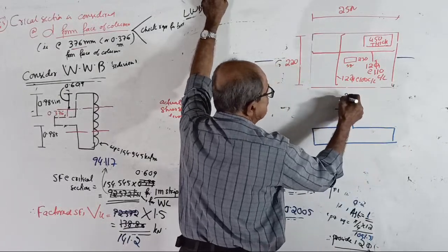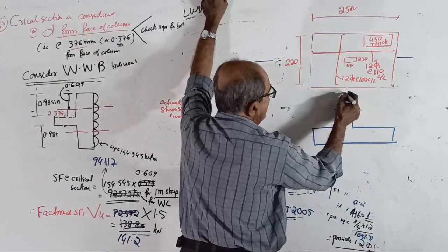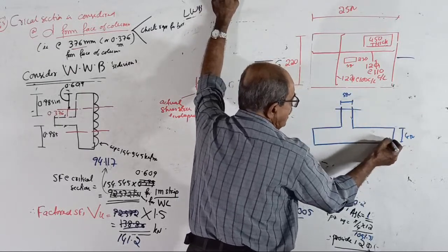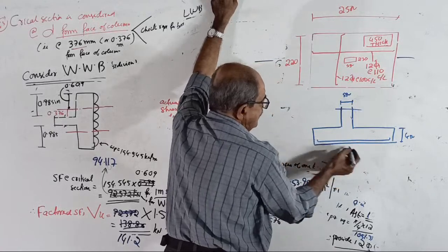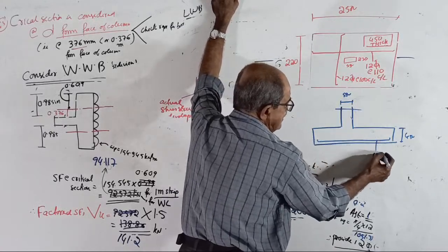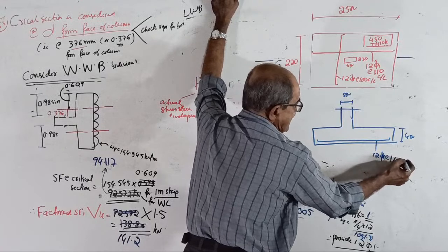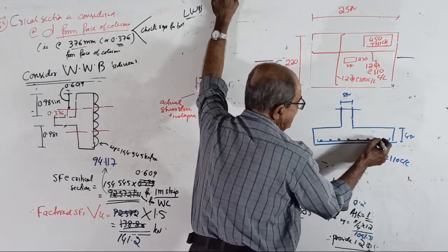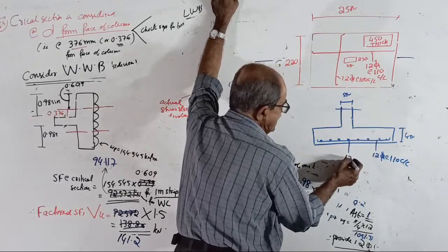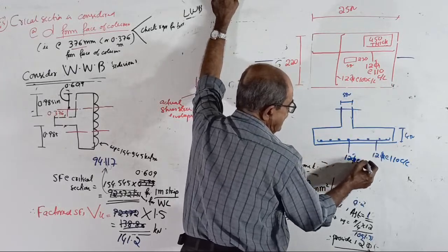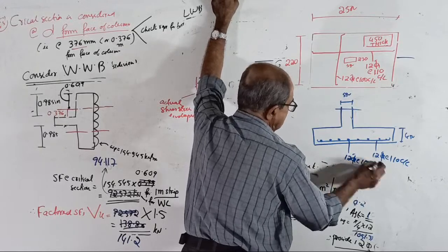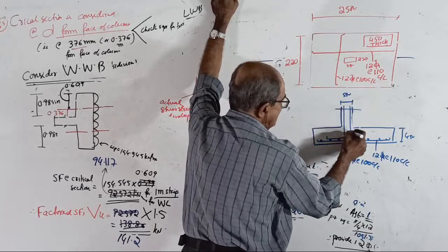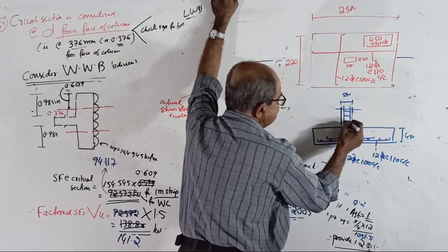Column side you are seeing is 550. Footing thickness is 450. You put lengthwise bar here, say 12 tor at 110 center to center, widthwise steel. Okay, place above, no problem. You can see this way, dot, that is 12 tor at 100 center to center. And column bars will be there, that will come and rest here. And then also stirrups will be there, show it.